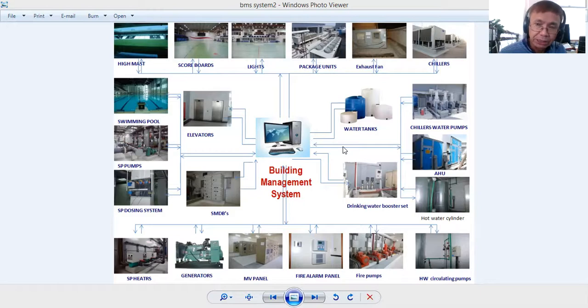Okay, so they will provide the enclosure or the control panel, then provide some indication lamps and selector switches on the front cover of the motor control panel, then some protection devices and some electrical equipment inside the control panel such as magnetic contactor, overload protection, miniature relays, terminal blocks, control transformer, etc. Okay, so this video will give you an idea how to design a motor control.